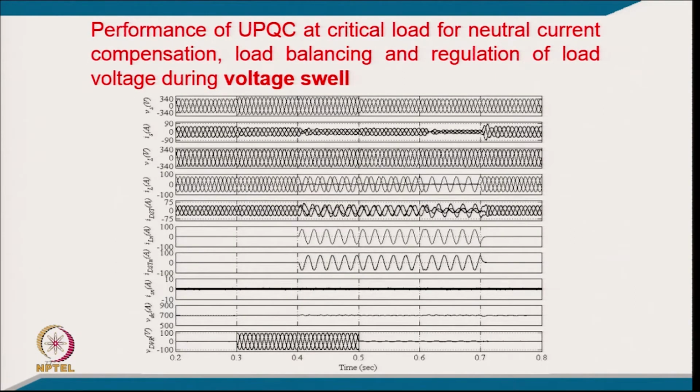This is another case when we have a voltage swell, like the UPQC performance. You can see from here to here there is a voltage swell; from nominal it goes a little higher, and because of the same power, the current goes down. But here one phase load is reduced, so the current reduces further, and here the voltage comes back to normal, but the current has to increase slightly, and here another phase load is reduced, so the current further reduces on the supply, but the supply currents are balanced and sinusoidal.